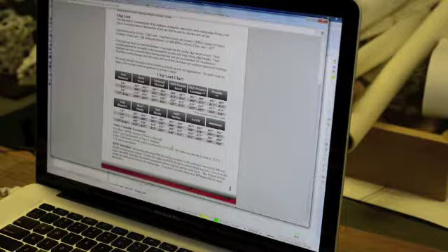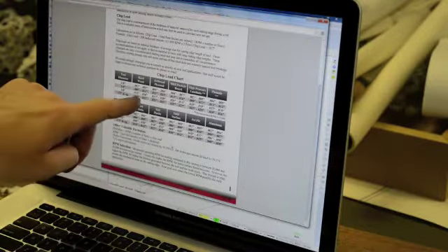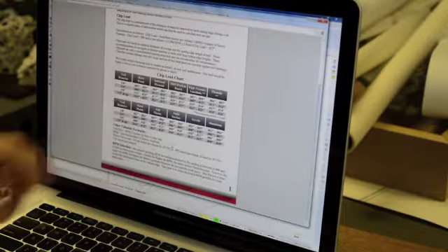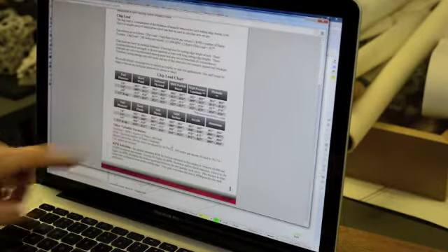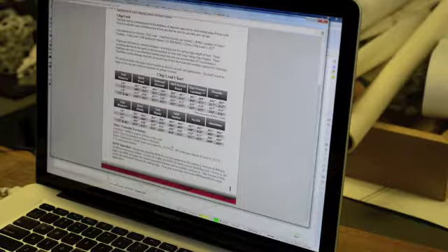We have a 1/2-inch tool downstairs with 3 flutes on it. So let's do 3 times, and the hardwood says we can try 0.019. We're going to do the feed rate we set in MasterCAM, which was 500, so let's do 500 divided by 0.057.